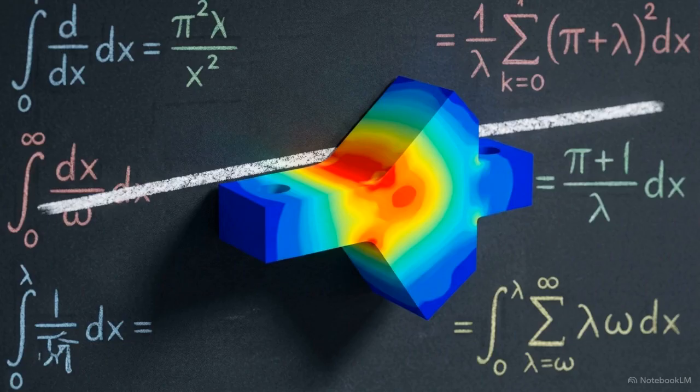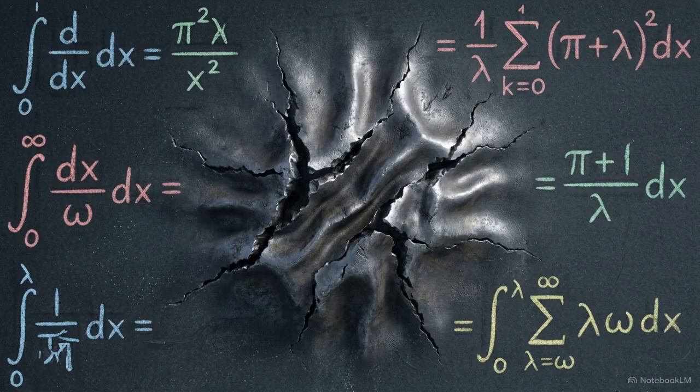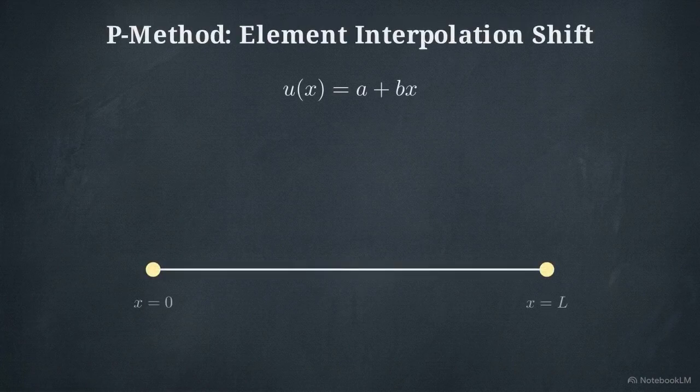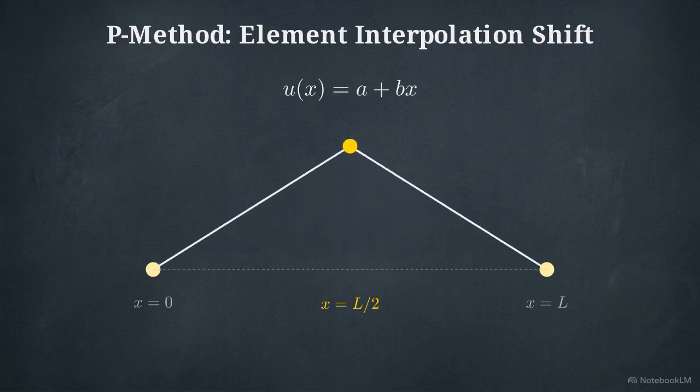But a straight line cannot accurately capture the true internal stress distributions of complex loading scenarios. Physical reality involves localized strains and variations that linear interpolation ignores. The geometric solution is straightforward. We insert a third data point, a new node located directly in the center of the element.